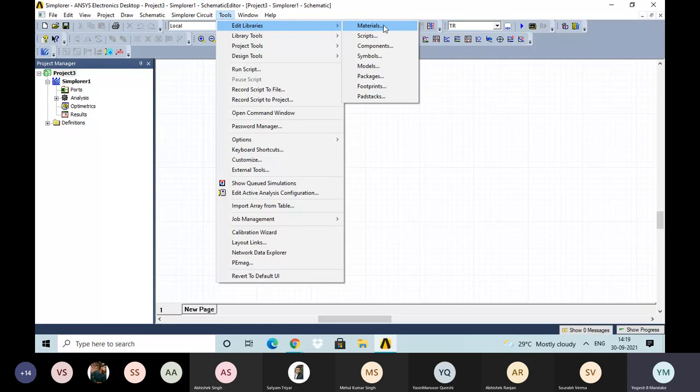If you want to edit the material, for example, if anyone works on developing a particular special material to enhance the performance of the machine, then you can add such type of material with its properties, because there is a standard format in which you need to give the details of that material, like name, then its BH curve, then there are different parameters from which you can make the table and you can add that material among the material list.